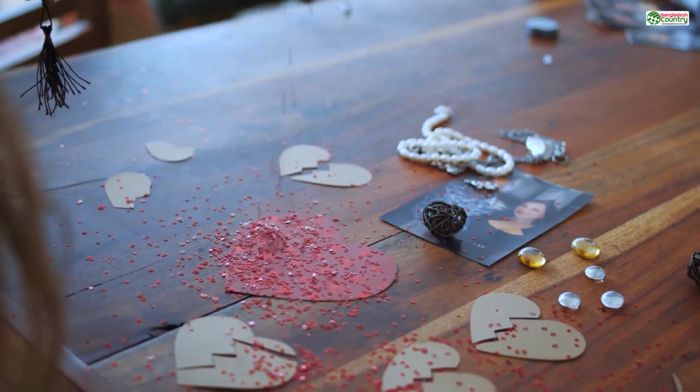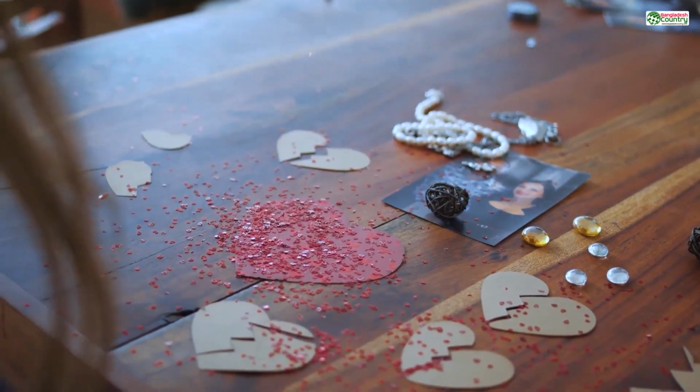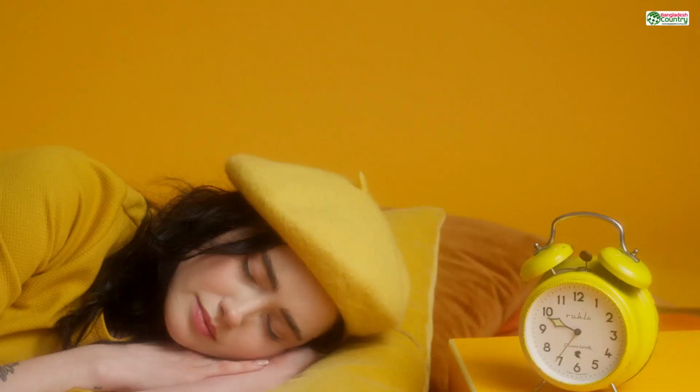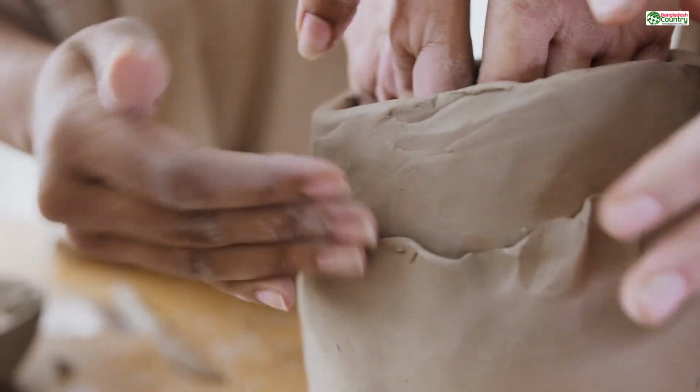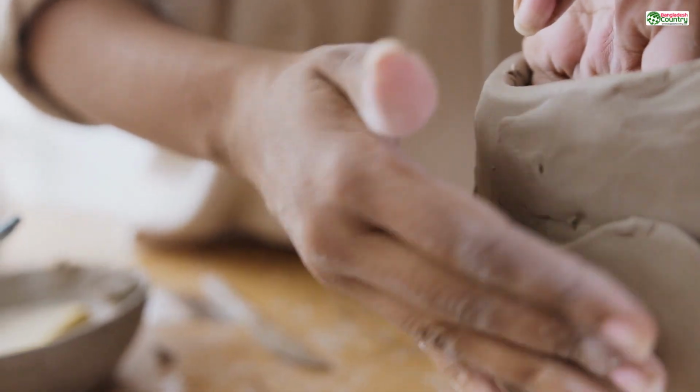Now you might be thinking, okay, I'll just make everything super thick. I'll make the walls 10 millimeters thick just to be safe. You can do that, but you're creating a new set of problems. The first is cost. Most 3D printing services calculate price based on the volume of material used.